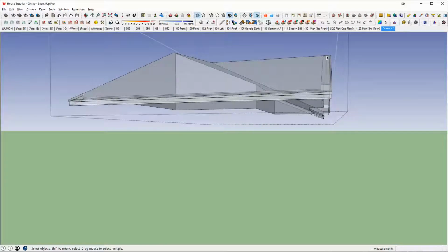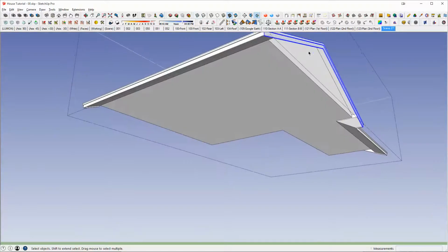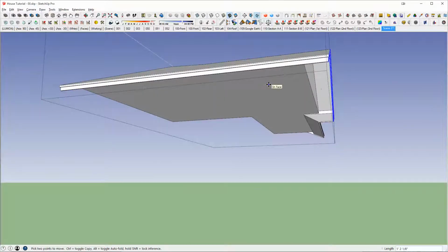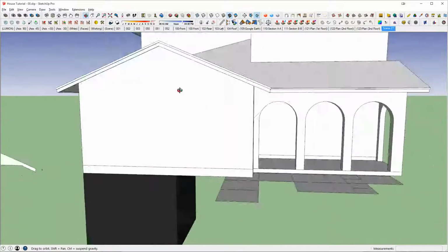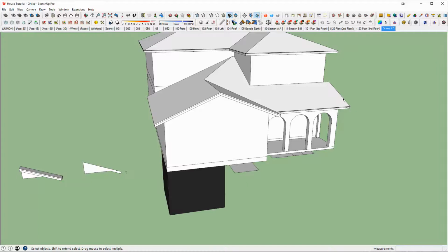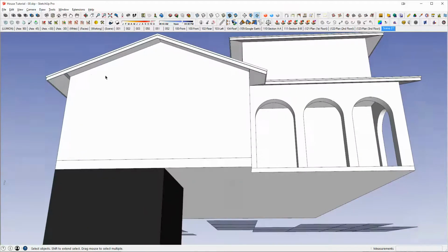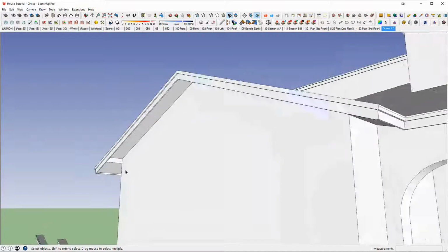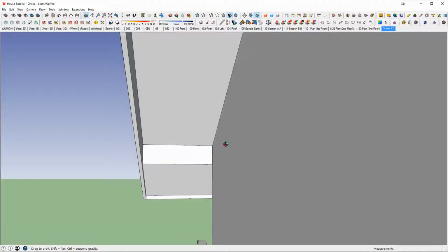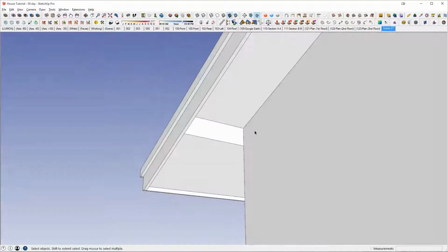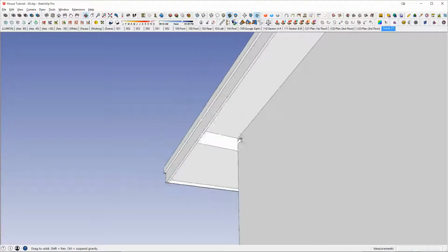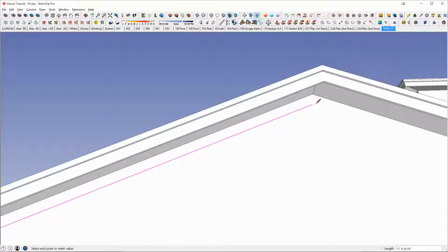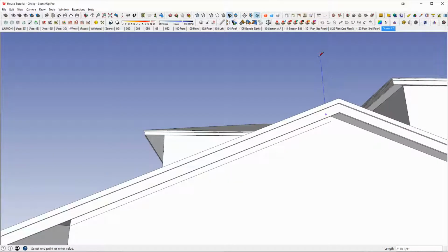Same over here. Again, that's another great reason why we have this wall cut back, so I can push this out 18 inches. And so there you go. There's your 18-inch overhang for the gable end, which leaves plenty of room to add trims and whatnot. As you can see, we are missing the soffit, but that's, again, an easy fix. I'm just going to draw a line touching the parallel line we're looking for. I'm going to draw a line that goes vertical.